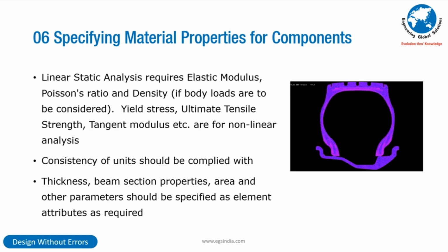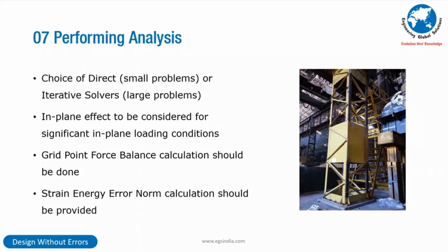In this particular case, the sealing of the tubeless tire happens because the air gets trapped between the tire and the rim. Pascal's law, equally transmitted in all directions, effectively seals it. So how much is the air entrapment there will help you to affect the sealing on this. This is the study for that. While performing analysis, choice of direct or iterative solvers. I've seen people using direct solvers and iterative solvers, and sometimes it takes a huge amount of time to solve. Why? Because the model is ill-conditioned. Singularities are there. That is the reason.